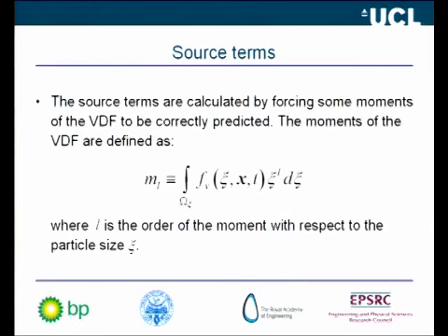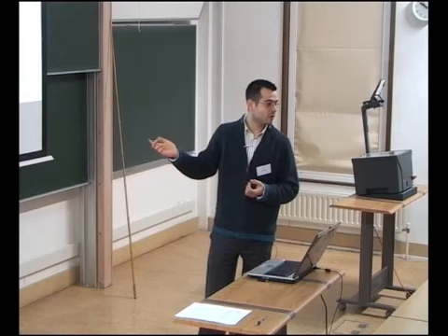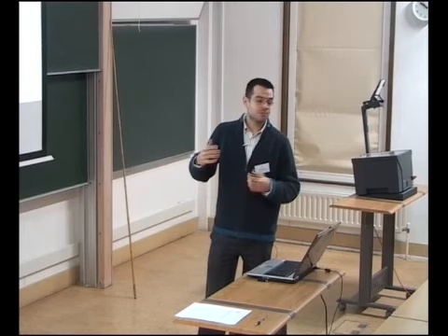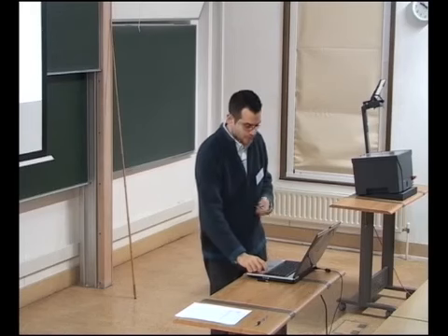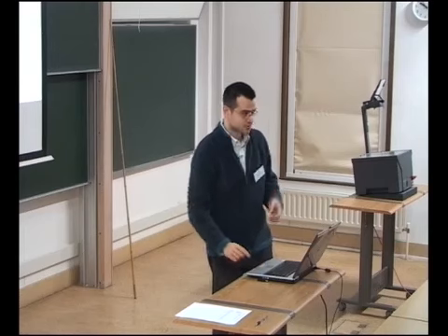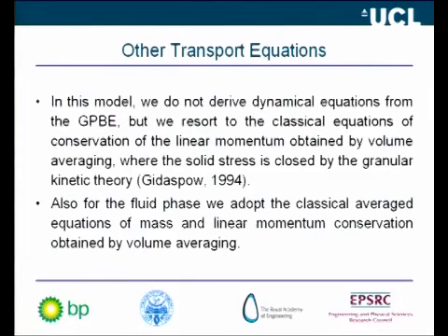Very sensitive. So in order to calculate the source terms, what we do is we force the VDF to predict correctly some moments of the volume density function. The moments of the volume density function are defined here with respect to the size of the particles in terms of these integrals. So we force the VDF to satisfy some moments, and by requiring this, we can calculate the source terms in the two transport equations that I showed before. This is the way we calculate those source terms.